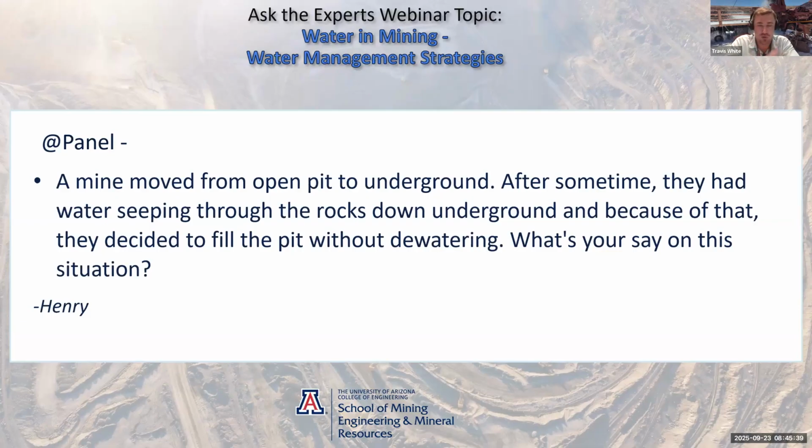Waste rock typically has a porosity in the region of 10 to up to 25%, depending on how coarse the waste rock itself is. So they've actually exacerbated the problem potentially, or definitely. Number one, they're going to reduce any water that they would have been losing to evaporation, so the volume of water that they'll ultimately have to manage is going to increase.